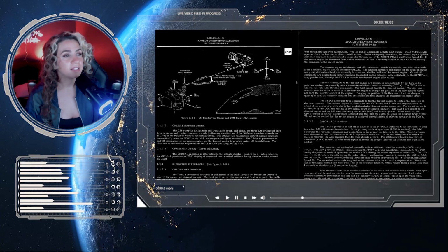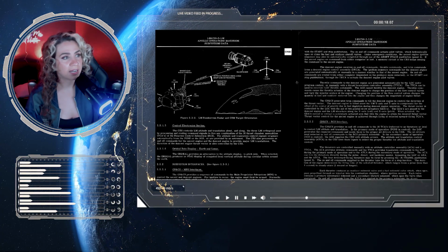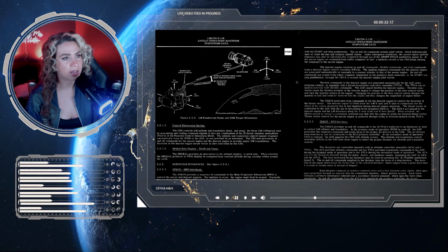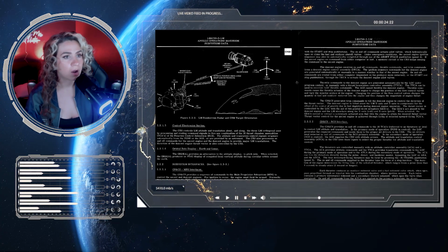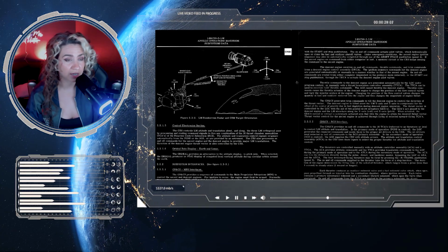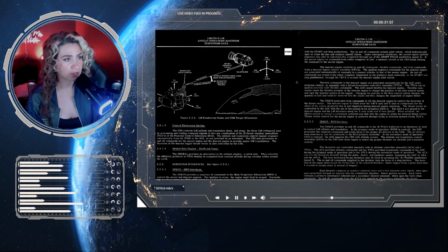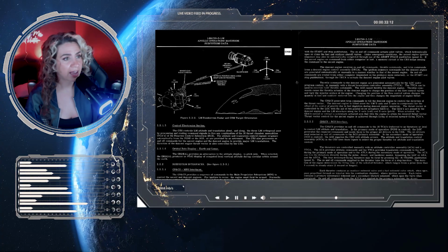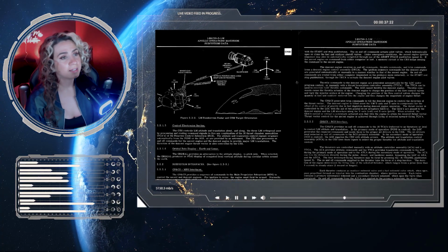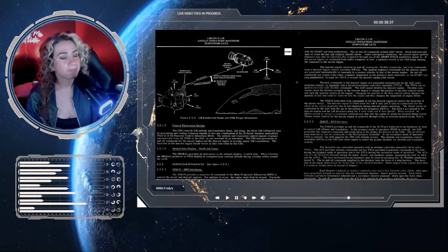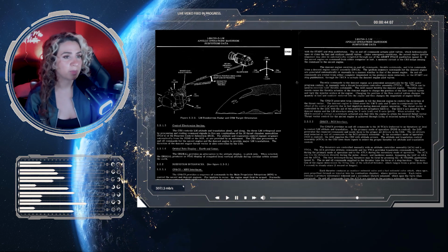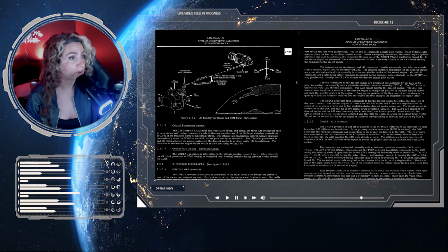DECA. The ignition sequence commands for the descent engine are generated automatically or manually in a manner similar to that of the ascent engine. On and off commands are routed from either computer, dependent on the guidance mode selected, or start and stop push buttons through the DECA, to actuate the descent engine pilot valves. Throttle commands to the descent engine are generated automatically by the LGC under program control,